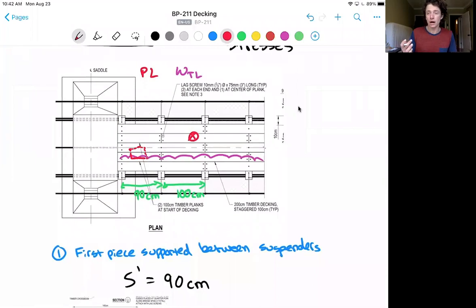So we have two options here. First, we could have a simply supported beam, which we'll consider that first beam here to be simply supported because it's fixed at the tower end, and there can be some elongation on the walkway side.